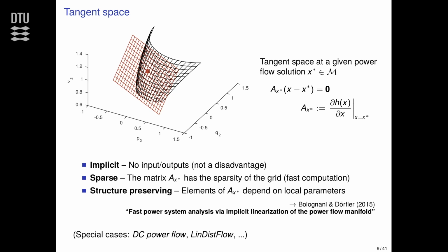And many of you have probably already seen linearizations of the power flow equations, like the DC power flow, the LinDistFlow, and others. We're not the first ones to do linearization of the power flow equations, but these are actually special cases of this one. Depending on where you put your linearization point and other assumptions you can make, you get all the other linearizations that you have probably seen in the literature.